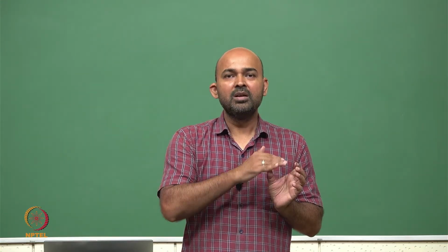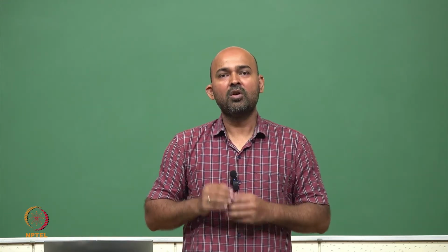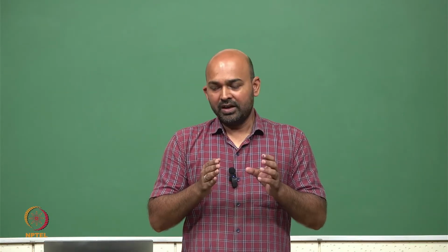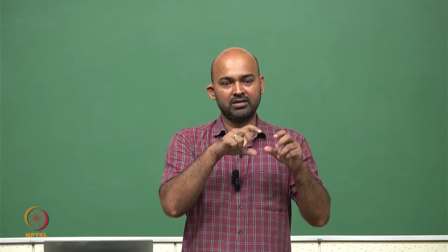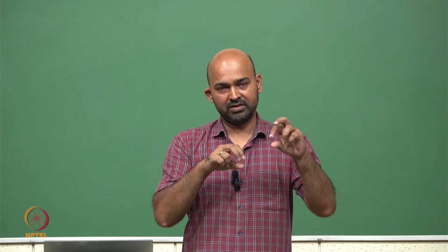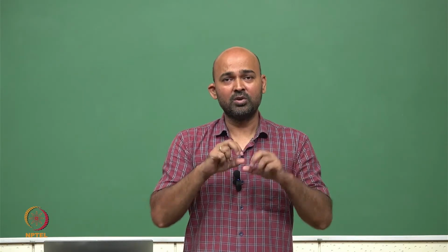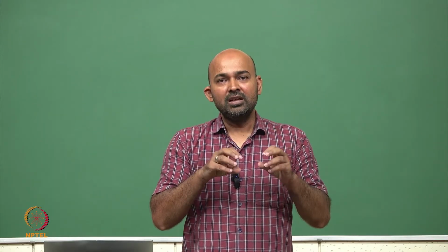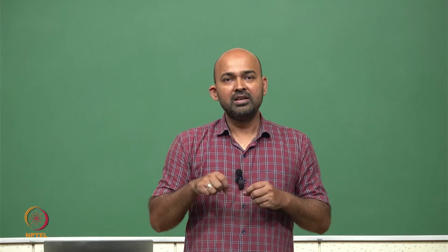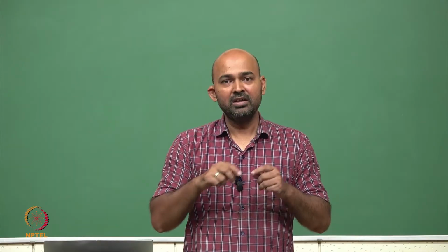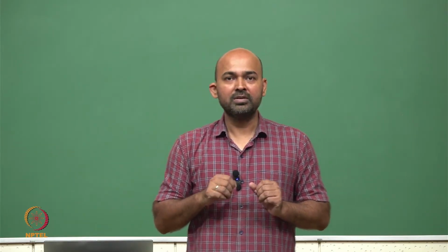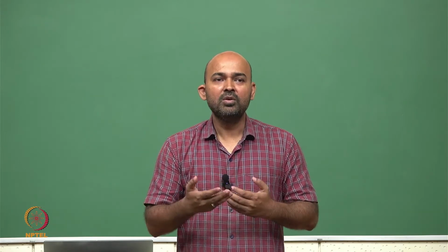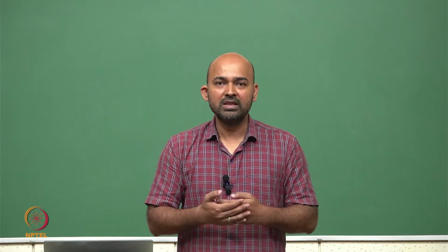Low pass filter will pass only the low frequency and cut down all high frequency signal. Here you can clearly see, once we put a capacitor in series with R1 and parallel to R2, this acts as a low pass filter, and we can clearly see it in the FFT as well. Now all the high frequency components are removed from the output. So this is how we can improve our signal to noise ratio.